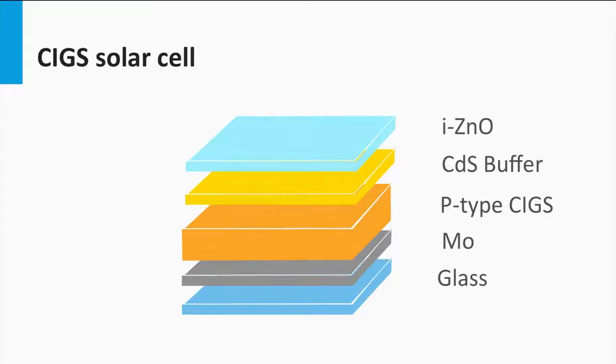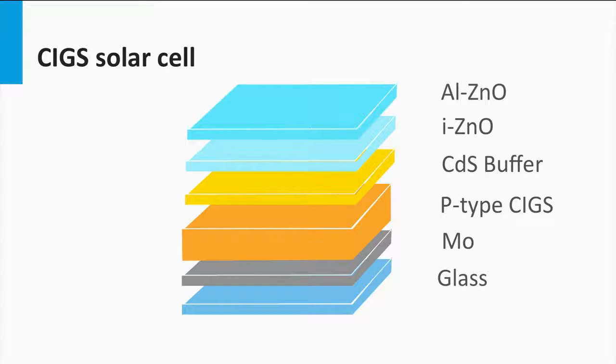This layer is referred to as the buffer layer. The n-type region is extended with an n-type TCO. First, an intrinsic zinc oxide is placed, followed by an aluminium-doped zinc oxide. The aluminum doping makes the zinc oxide n-type. Similar to some concepts of the thin film silicon technology, the aluminum-doped zinc oxide acts like a transparent front contact for the solar cell. On top of this transparent conductive oxide, anti-reflective coatings can be placed, as discussed for the crystalline silicon technology.